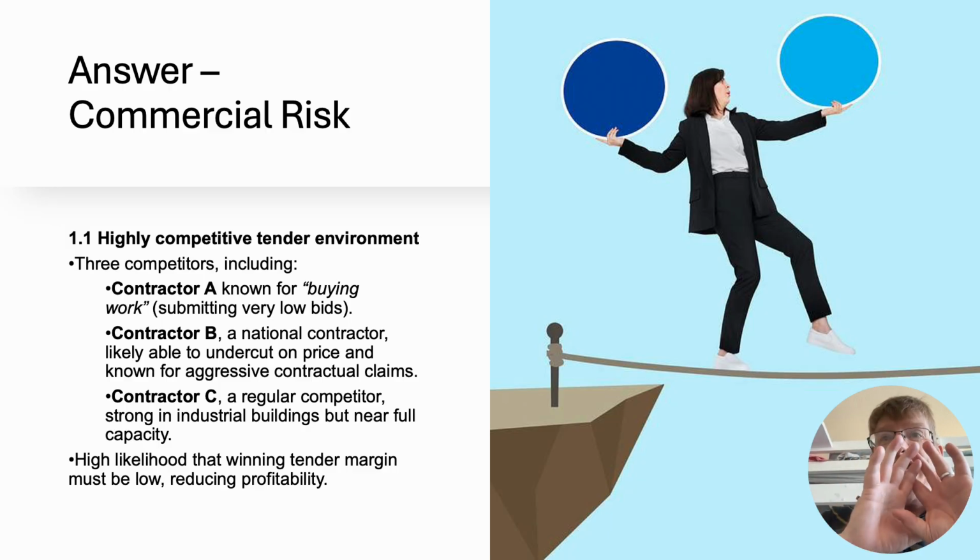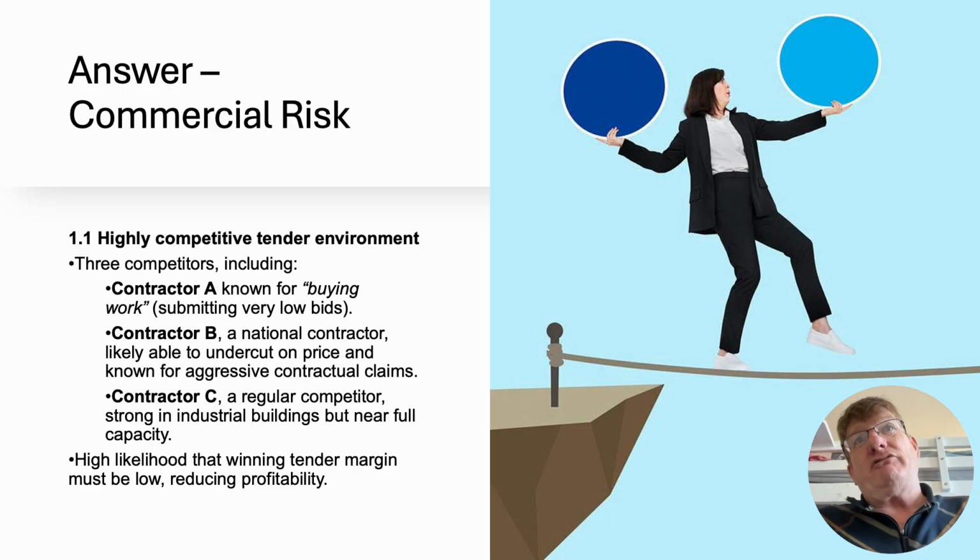Because I can be a lot more analytical now, which I can't when I'm doing an elemental unit rate. It's more generalized when I'm doing an elemental cost plan, or a cost estimate based on the gross internal floor area. I'm really relying on quite accurate historical data, and also on the methodology set out in the NRM, which makes it reliable, consistent, certain, generalized. And what I mean by generalized is that I can compare it, and it gives me all of that.